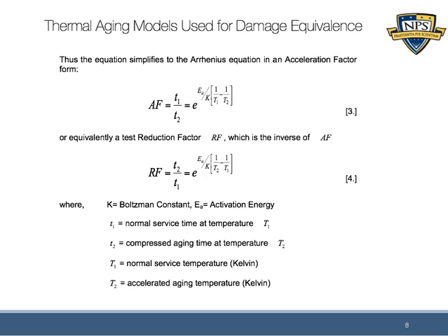So how can we find it faster? And if we do find it faster, so let's say maybe we don't know exactly when it occurs in reality and we're interested to understand that, we can set up a test at extreme temperatures to find the failure faster, and then essentially deduce out of that when it would occur given the life cycle of the system. What the component or the system would see in reality.